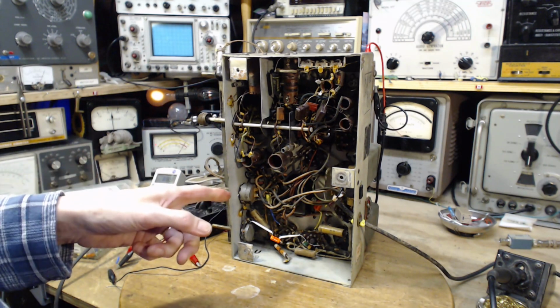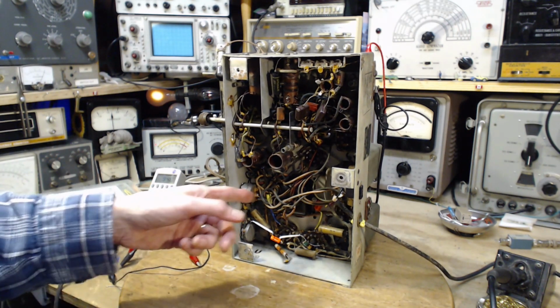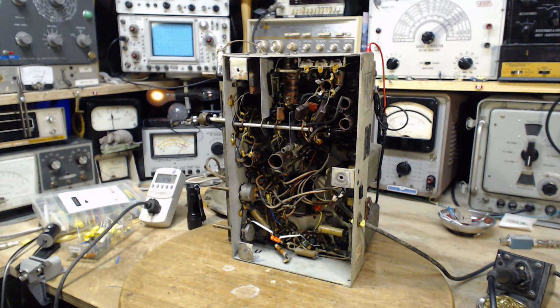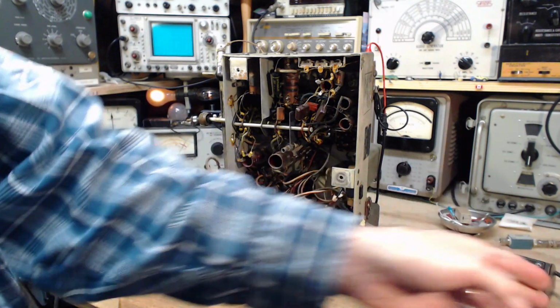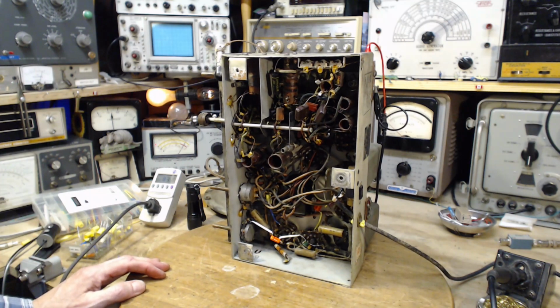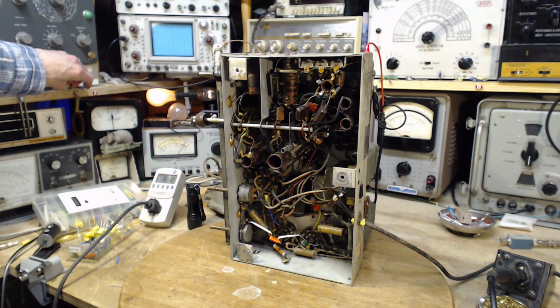Now that particular capacitor I put in there is going to sustain B+ across it. So I put a strong capacitor in there, a 600 volt capacitor. Some of the other capacitors I've installed here are lower voltage capacitors because their duty is lower voltage. So, okay, we can give it the full shot here.